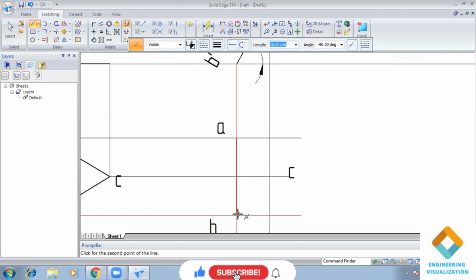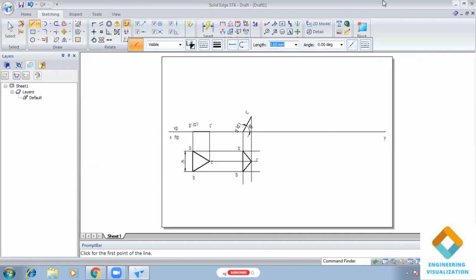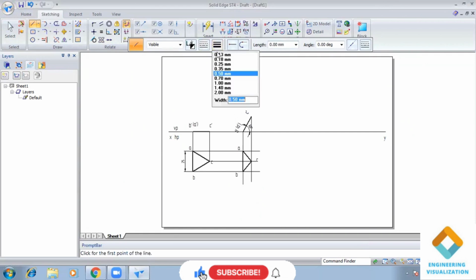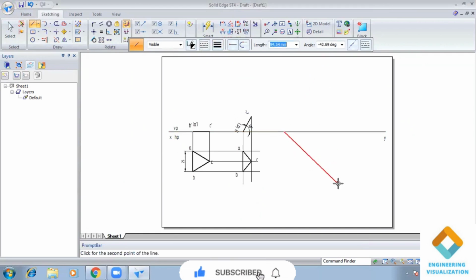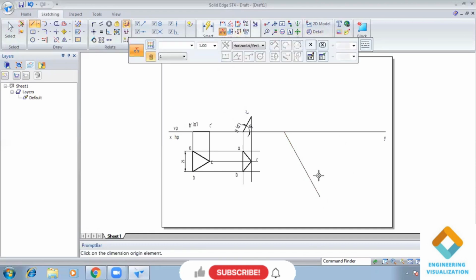Okay, so make sure you select like this. Okay, the cross mark should appear, the intersection mark. Okay, the second position top view is completed. Now the third position, so we need to draw an angle line. So give the angle in negatives. Okay, here in the angle you can type minus 60 degree. Okay, and find out the angle here using angle between command, 60.